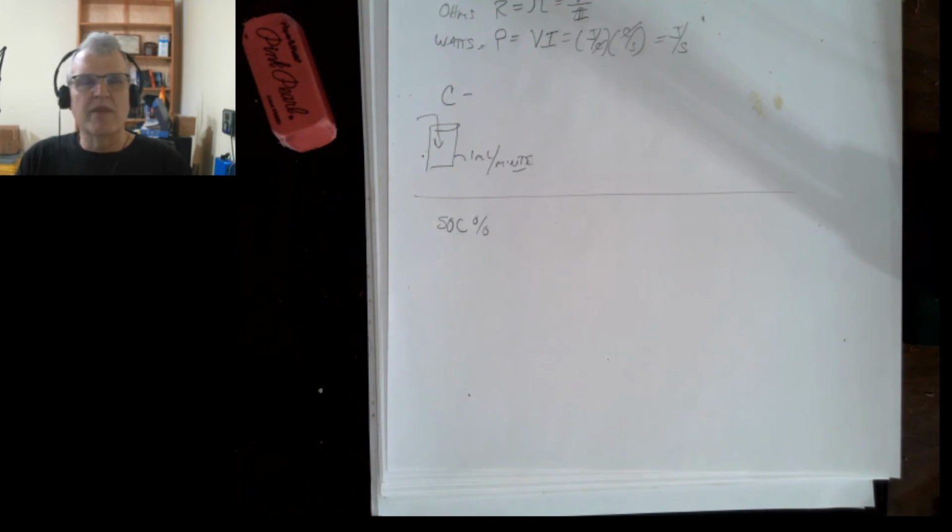So it gives you a general idea of what you want to stay away from when you're building your do-it-yourself Powerwall. You would never want to get anywhere near the maximum continuous discharge rate for your battery. All right. So the only other thing left is the forming of the battery, with how much in parallel and how much in series, and what the two different things do. We'll do that after we look at what you want to do when you go through your batteries to test them.